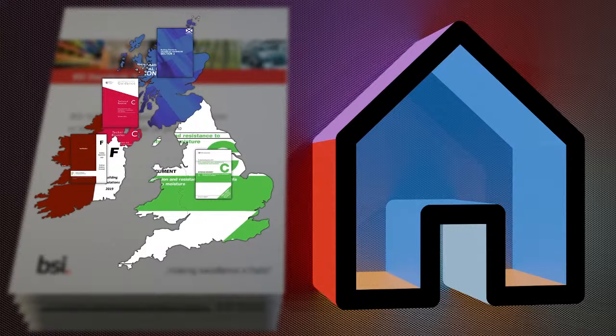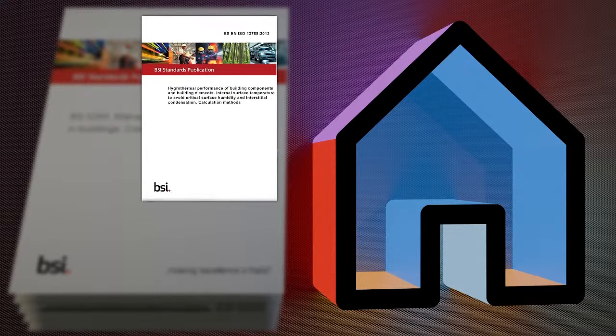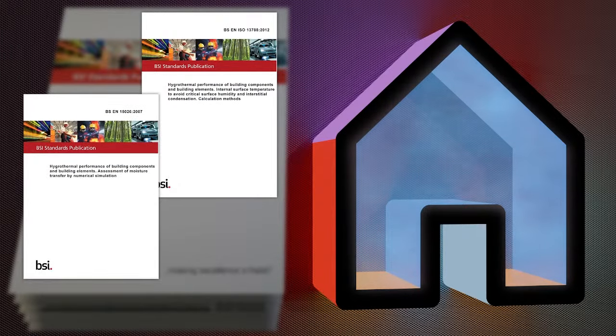As well as offering prescriptive advice to specifiers, BS 5250 also references appropriate calculation methods and outlines where their use is appropriate. For moisture assessment, the two methods used are BS EN ISO 13788, which is applicable to most common situations, and BS EN 15026, a more complex and comprehensive assessment for more specialised applications.